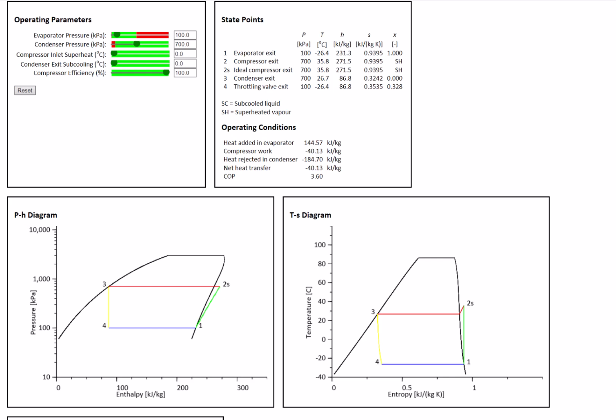That's a little bit easier to see on the TS diagram because this axis is temperature. So the exit of the compressor here, which is the inlet of the condenser, is a little bit superheated, so a little bit higher. Anyway, that's the highest temperature in the cycle. So the lowest temperature in the cycle and the highest temperature in the cycle. And the reason I'm talking about temperatures here is because that's the main thing that the two operating pressures control. As we move those pressures up and down, it's going to change the temperatures in the evaporator and the condenser, and that'll determine the temperatures that our vapor compression system is working between.